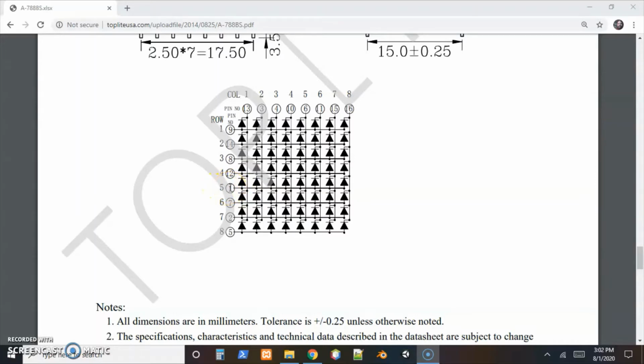Once you find pin 1, you just count around and check the data sheet for which ones are anodes and which ones are cathodes. Cathodes head back to ground, anodes bring the positive voltage in. You do have to actually check that on these, because it seems like there's not much rhyme or reason when we're looking at the outside after it was optimized for the inside. So let's go back to the circuit.